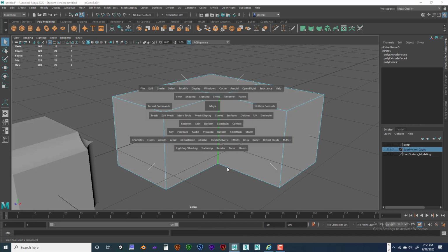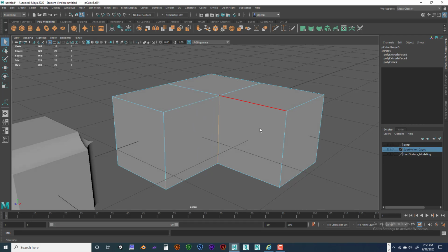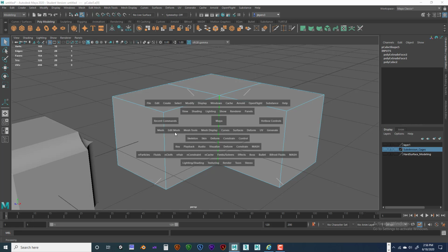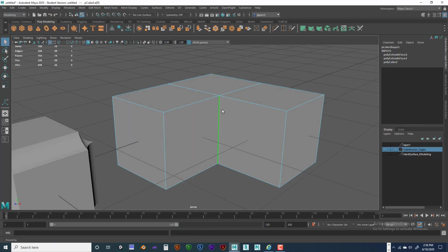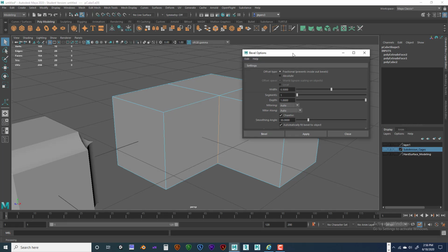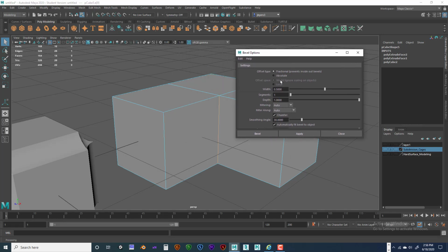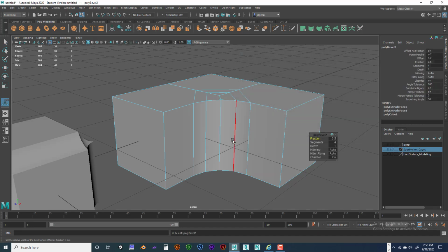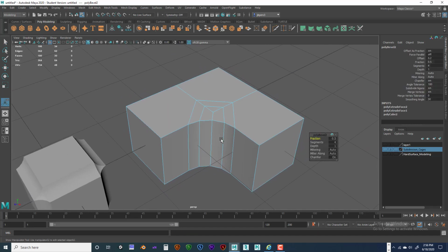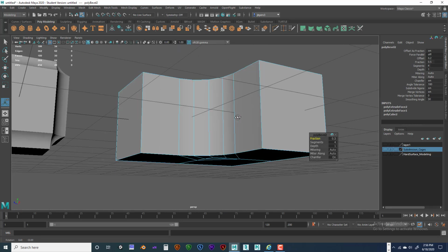We're going to do inside bevel here. These are the hardest bevels to do, not outside edges, but inside edges. So let's go ahead and select that, and let's go to bevel, and let's go ahead and get that reset, and set that to 4, and we'll just leave it the way it is. Okay, so this is what basically the bevel tool gives you.